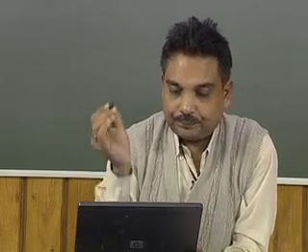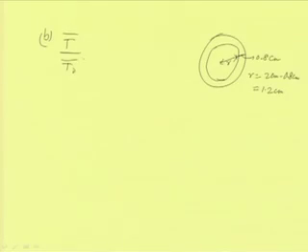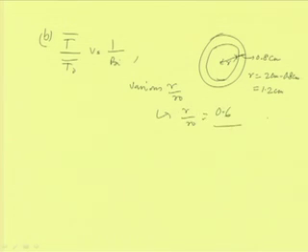And then what we will find out is that for part B we have to get T bar by T naught bar from the plot of this versus 1 by Biot number, for various R by R naught, and in this case the R by R naught is equal to again 0.6. Okay, that is maintained, and then all other things are known.